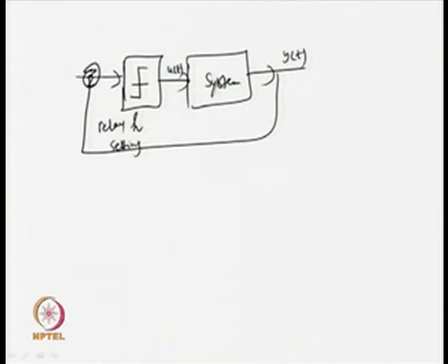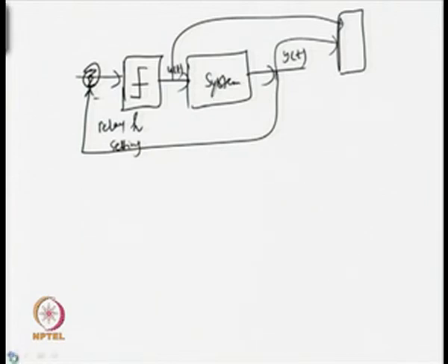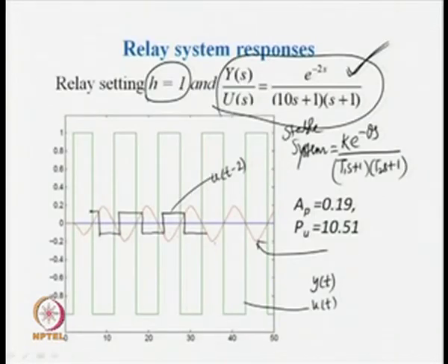When you are going to simulate this using MATLAB or Simulink, you have to be very careful how you obtain the delayed input signal practically. If you simply connect y(t) or u(t) to the scope, the type of signal you will get for a second order system is this one, the red and the green one. The type of signals you will get will be of this form.